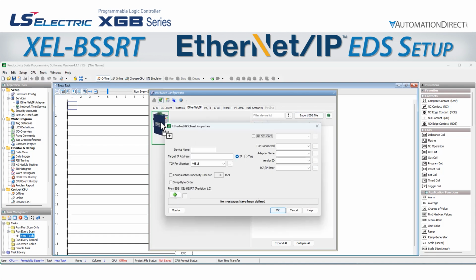We can drag and drop it over to the left to create a client connection for this EDS. We will use a structure and call it XEL_BSSRT. Our device name will be XEL_BSSRT as well, and our IP address is 192.168.27.120, since this is the IP address we set for the BSSRT in our video on configuration.